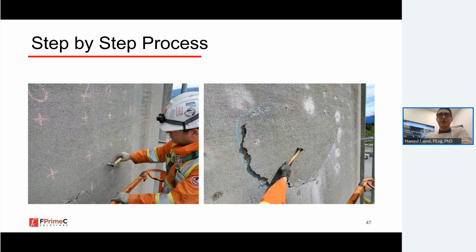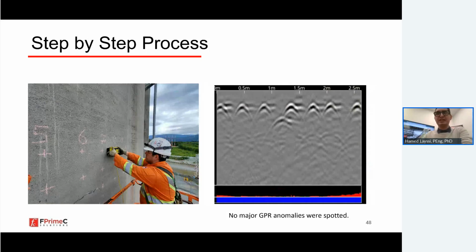So this beautiful heart was broken out of the concrete. We wanted to see what's the reason, and if it has expanded beyond this. So we did GPR as a first stage. We identified a very regular rebar mesh in the shell. If you are a little bit careful and curious, you can see the second layer of reinforcement here as well. Not so clear, but with a little bit of post-processing, we can give it a little bit of gain and see that level of rebar as well.